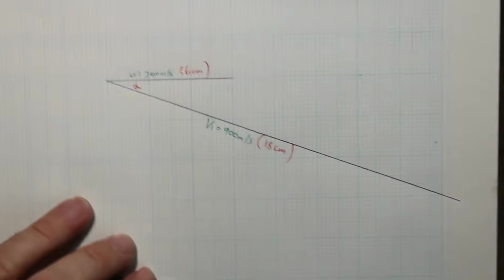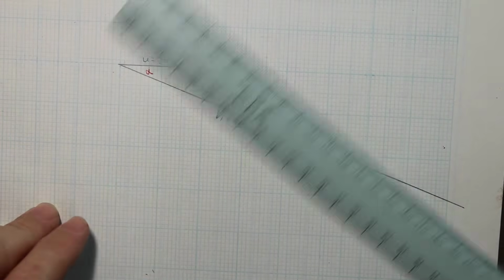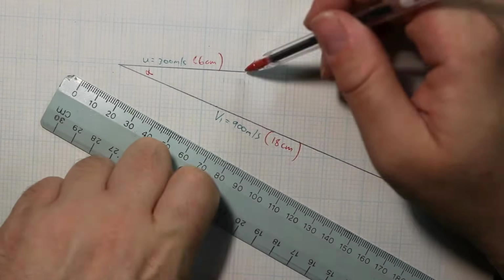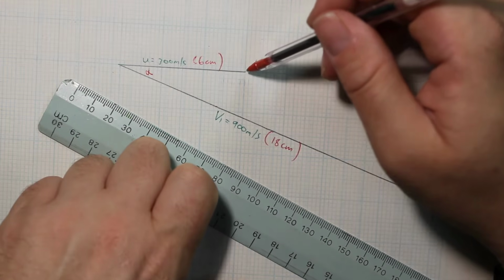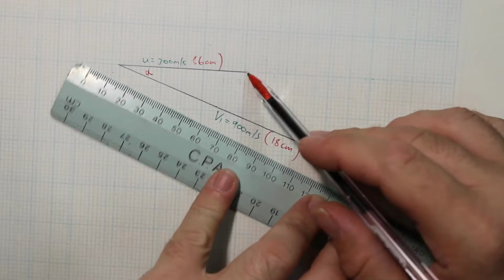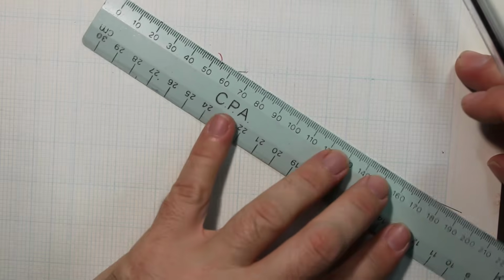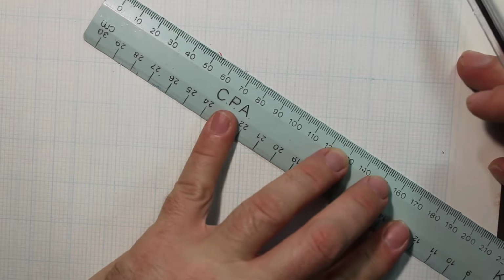See that? Now it gets quite easy, because this side over here has to do with the angle of the blade, the inlet and outlet blade angles. So now we just join that end to that end so that we can get the relative velocity.